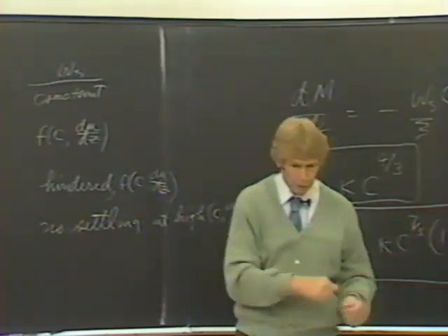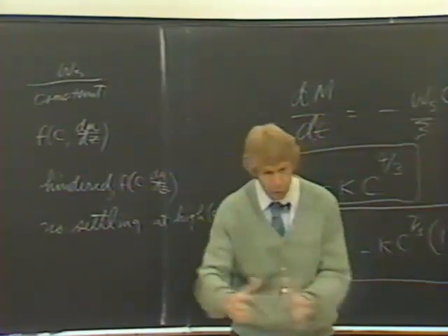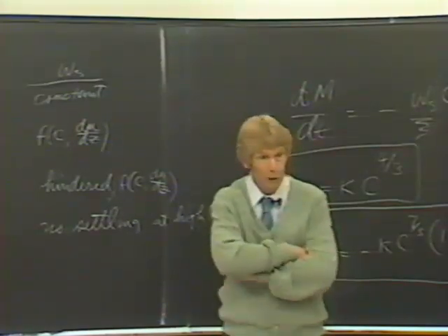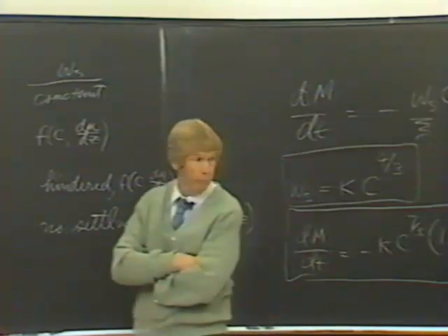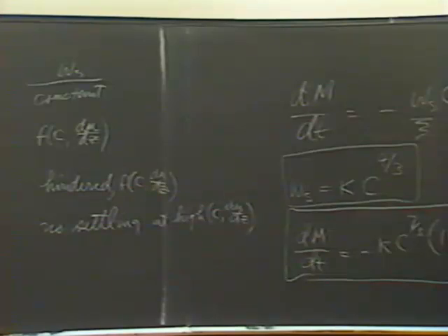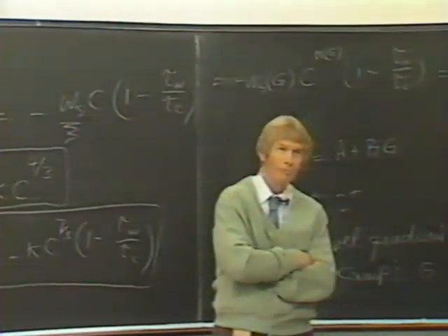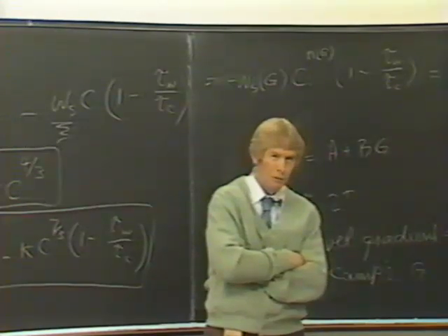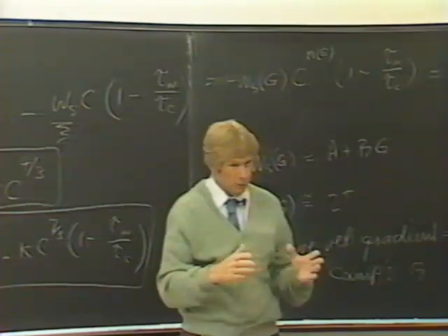During this period, if the concentration is very high, you may have a slurry, and as you saw, it takes some time for a slurry to form aggregates and settle. You may not really have very much deposition here. The concentration is really high, with the result that the material just moves back and forth. But if a portion of it turns off into an enclosed harbor where the velocities are low, then it carries the material in there and it will settle there, or in the lee of a wharf or some place where velocities are low. Whereas out in the current, it's just carried back and forth.